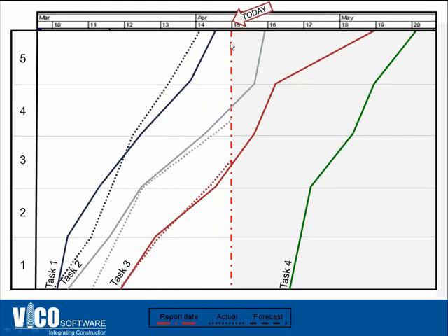And when you get to a certain point, you generally say that we're a little bit behind on this task. Actually, we finished ahead of time on this task. We're a little bit behind on our framing tasks, and we're on time on our drywall task. So when you look at this progress inside a Gantt chart view, you'd say generally we're doing okay. However, with the forecast, you'll be able to see where problems might occur in the future based on the production rate and the trends that you're tracking.